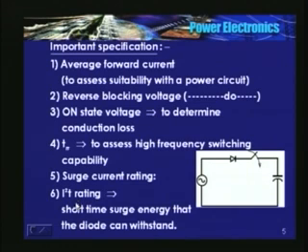It is an indication of the short term surge energy that the diode can withstand. This is required to choose a suitable fuse in the diode circuit.